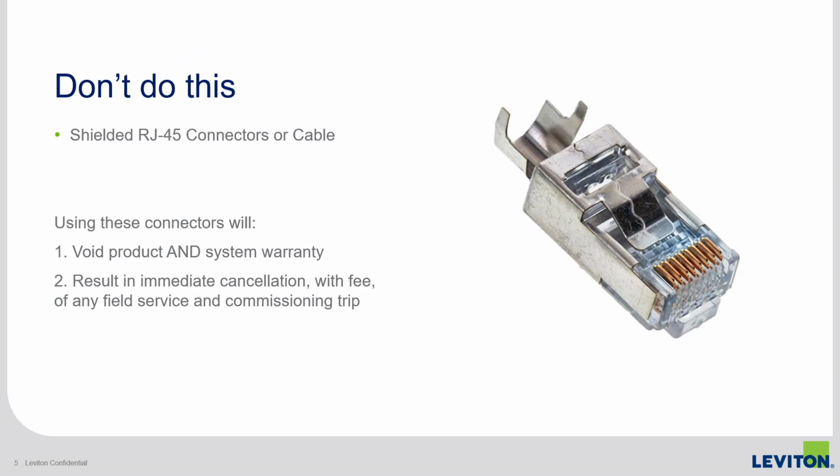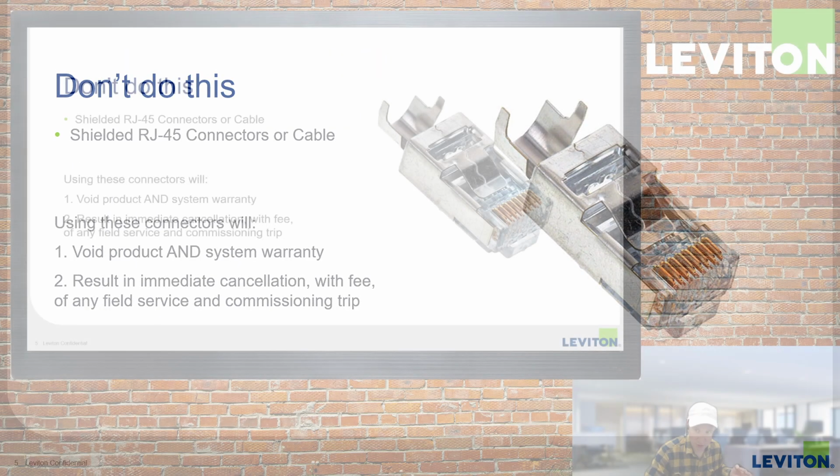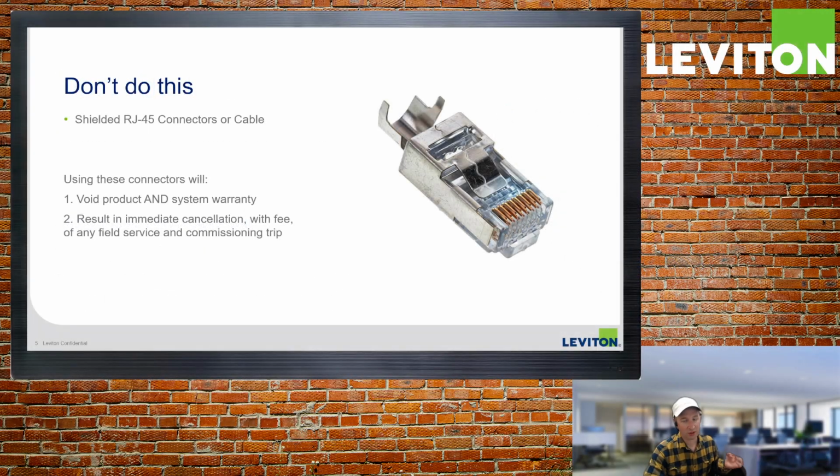What are some things that you don't do? Okay, now the consequences for these things are severe, so please pay attention to this. First, do not use shielded RJ45 connectors or cables. Our product is not designed for them.